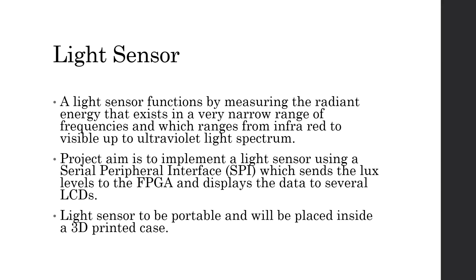The code used for the Arduino was copied from the information in Module 5 on Canvas. This means that for the time being, the Arduino is acting as a master, with the FPGA being the slave. This is okay for the time being, as the only other SPI device has yet to be implemented.